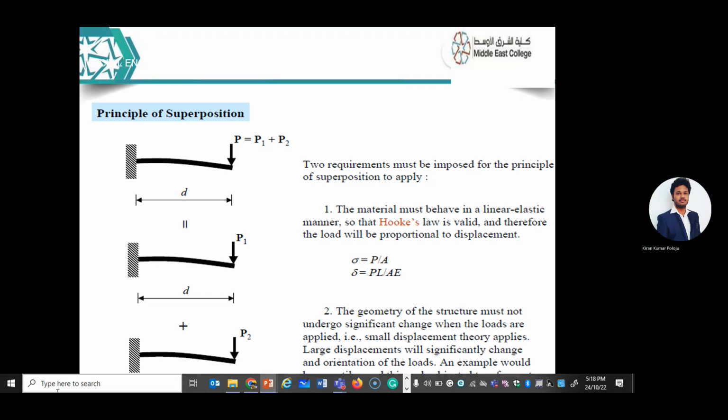And this load, you will get when you are applying load. I will explain at the equipment, but if I give you some information before that, then when I explain on the equipment, it is easy for you to understand. Okay. So, you will get the load when you are applying load. When you are applying load, on the dial gauge you can see how much load is being applied. Based on that, you get this load value. Once you get this load value, load by area gives you stress.